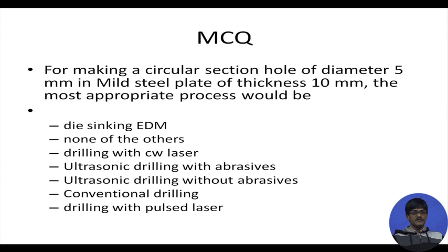Ultrasonic drilling with abrasives. Yes, this can definitely be used. But mind you, as this is mild steel, it will be a ductile material, and you won't be getting very high material removal rate with mild steel if you use ultrasonic drilling. Ultrasonic drilling without abrasives, well, then you will be without abrasives, and therefore your material removal rate will not be high, provided it will cut at all.